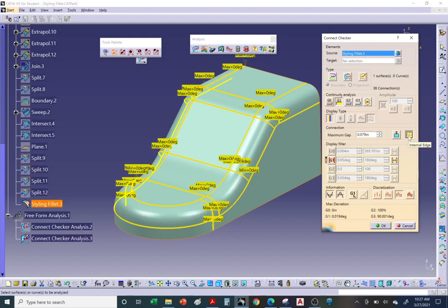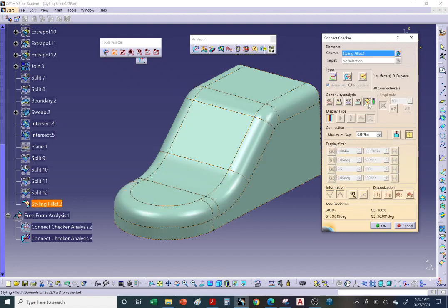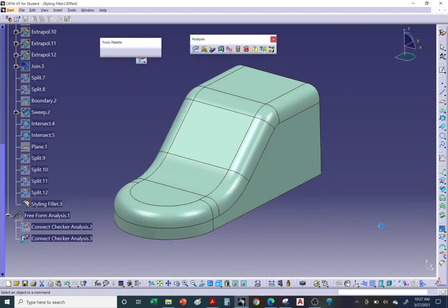All right, so we're almost done. Sorry if I put you to sleep. Here it's showing me all the errors, right? So this fillet didn't go as clean as we were hoping. Again, this is very common. Now, I didn't want all this ugliness. Usually it's just a few areas. Let me see what happens if I pick overlap. Let's check for overlap. And okay, nope, no overlap. So there's no overlap, so that's good.